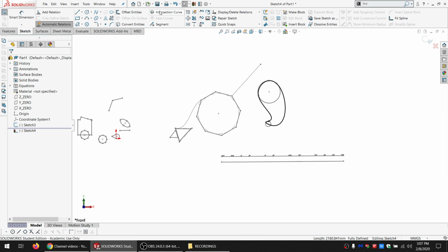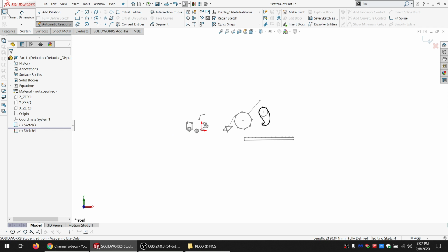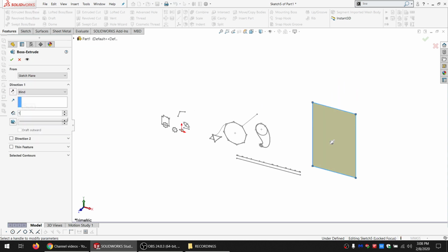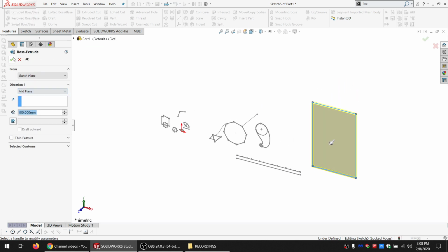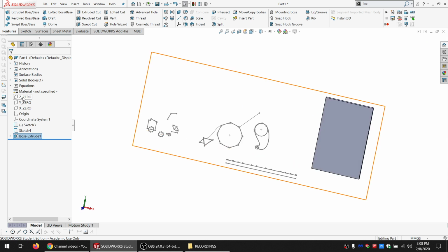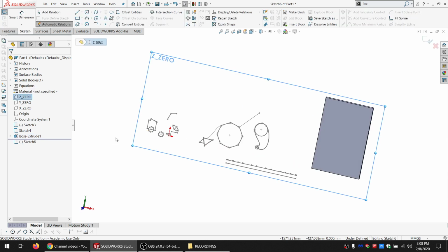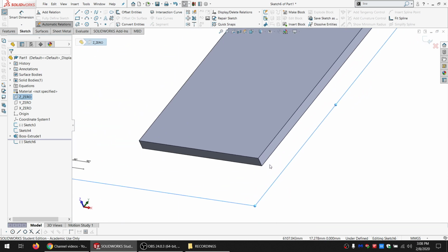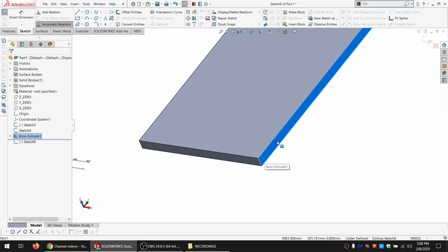And let's see. Intersection curve is a little bit different. Let's say first I need to make just a bit of geometry and make this 100 and midplane. Okay, so let me go back and make a new sketch here. And okay, so I've got this very important thing that I designed at some previous stage, and I just want a line that's right on here. What I can do is click intersection curve, and I just get a line right on there.